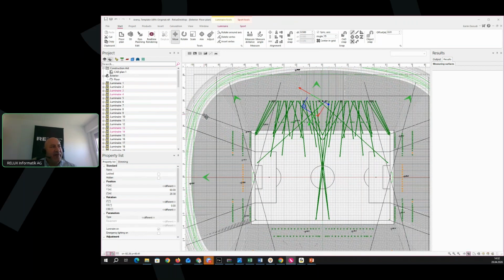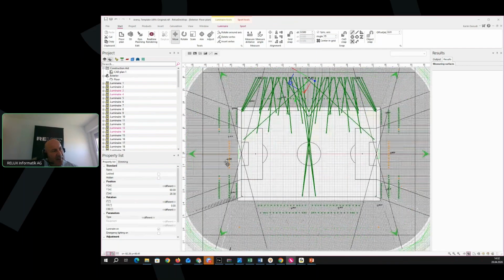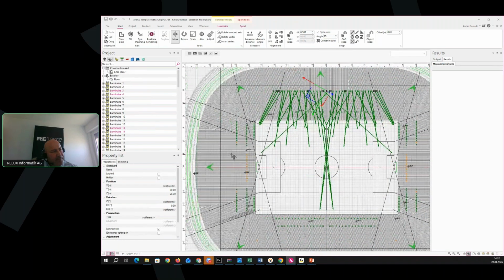Nowadays regarding UEFA or FIFA, you will always have an elliptical arrangement of the luminaires in order to fulfill the UEFA and FIFA standards. Why elliptical? Because you need to fulfill the vertical lux levels for the big broadcasting events, Champions League we are talking about here. If you don't have an elliptical arrangement like that, you will not achieve it with any other arrangement.